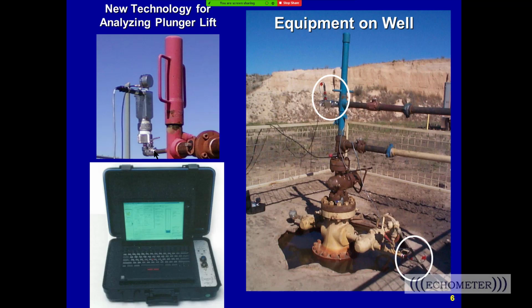So we have a question from Hector asking if the well must be prepared in advance to avoid different tubing sizes in the string. Oh, well, if you have different tubing sizes in your tubing string, then a plunger won't seal. You can't run the plunger. So you're going to have to set your bumper spring at the taper at the junction and just run the plunger from constant diameter. I don't think there's any plunger that can run in a 2 7/8 and 2 3/8 inch tubing taper.